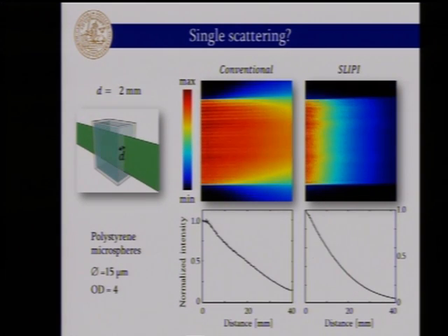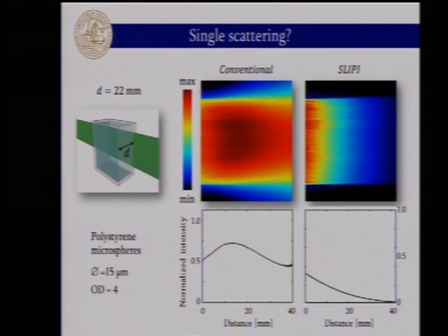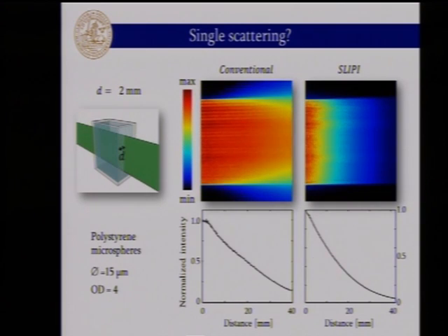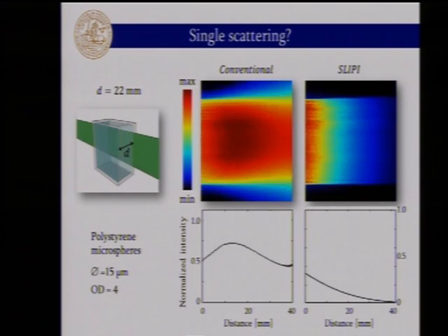Only the intensity is reduced due to the signal attenuation accordingly. So this is a very good proof that you extract single light scattering. And based on that, now you can use a technique to size droplets or find out the temperature or any quantities, because you know that what you get is really coming from the illumination plane and not outside.